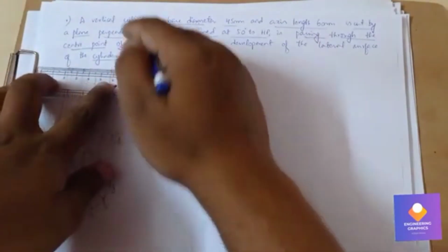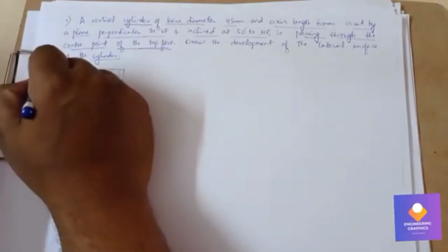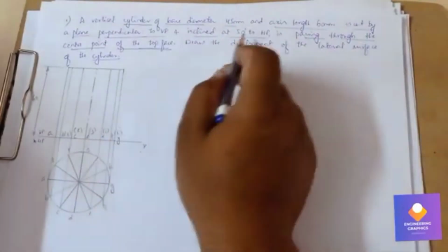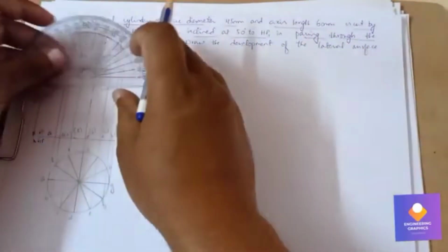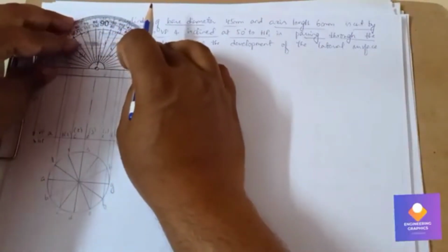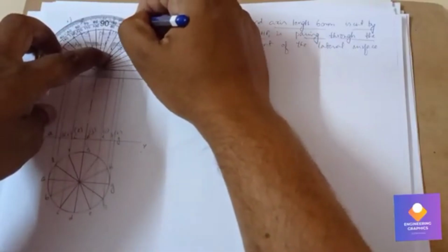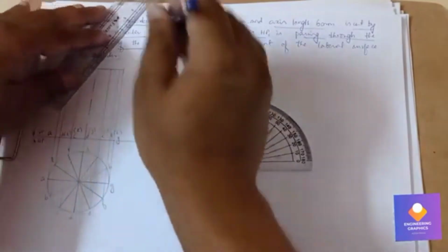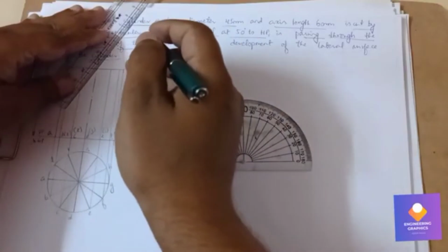You can see here, exactly at the top face center, we need to show the dimension. So dimension of 60. So here on the axis, we need to draw a section plane of 50 degree exactly from the top face. From the center of the top face we keep the protractor and mark the angle of 50 degree. Draw a section plane passing through that angle point.